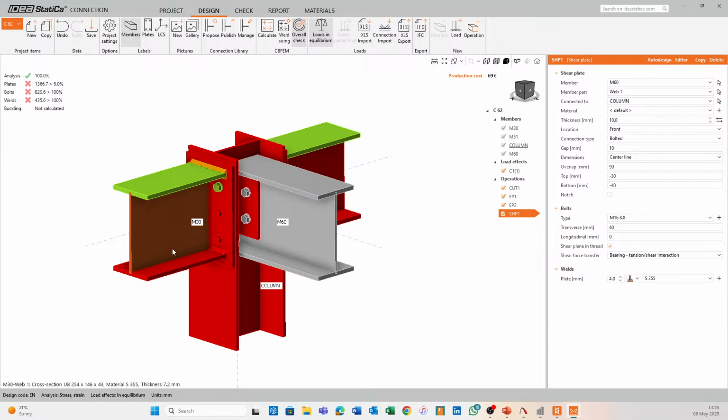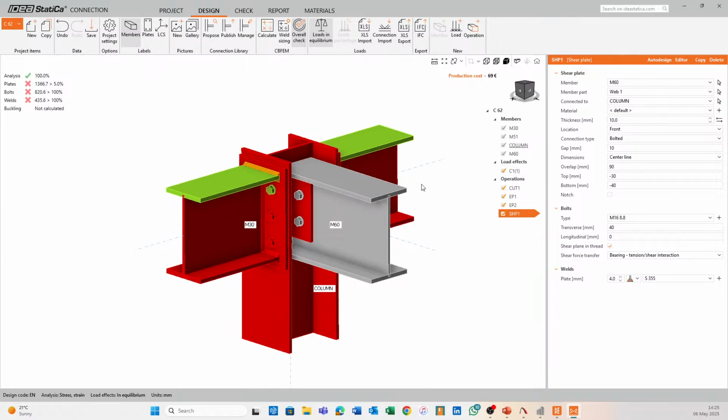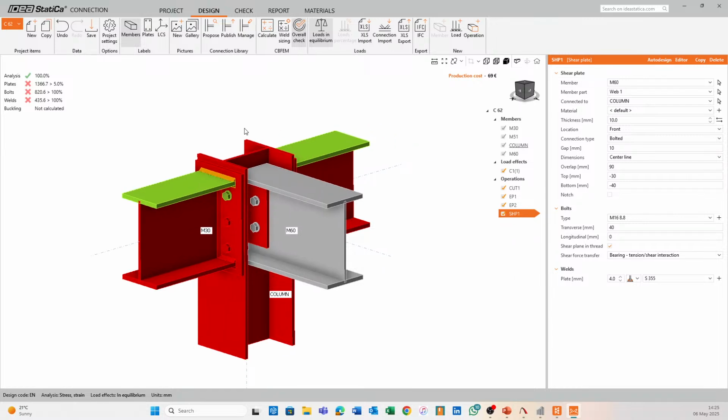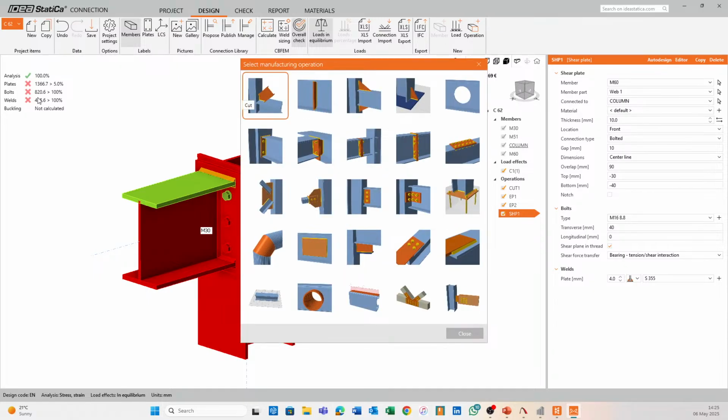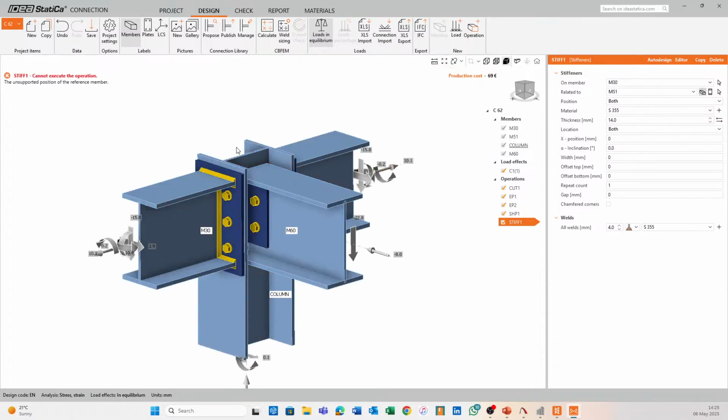It's a 5-meter column or whatever it might be. We might find ourselves in a position where upsizing the member is really an expensive approach. IDEA StatiCa allows us to experiment with the use of stiffeners, stiffening plates, ribs, you name it. So the first thing I'm going to do is put a cap plate on this column. Let's take note that plastic strain is sitting at 1,366.7%. I'm just going to add a stiffening plate to the top of the column, and we're going to rerun our analysis.